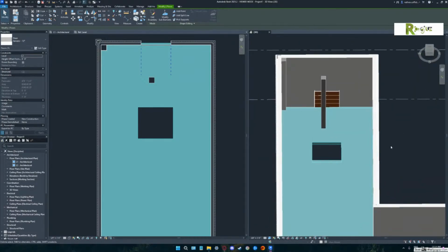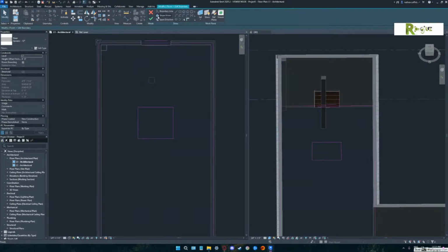And that shape, you can do any kind of shape. So if you have a recessed floor in one area, you would just draw another floor and add your stair or whatever your interior wall is that closes up that space. You can add multiple islands. You can add round holes. A majority of things you need to do. So if you did that and then did a fillet command to trim those out. Wait, don't do that yet, because you have to have closed shapes or it won't know what to do.